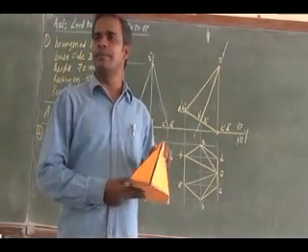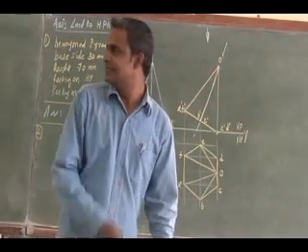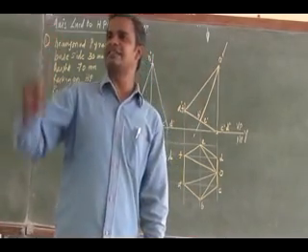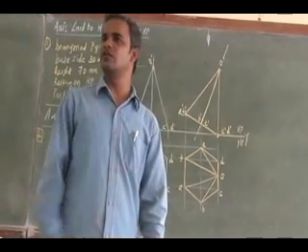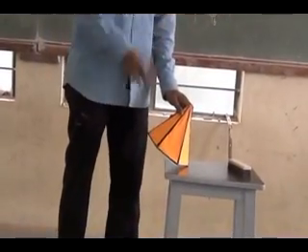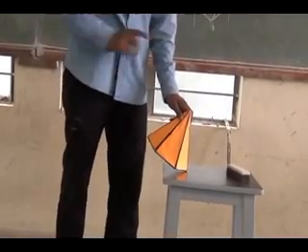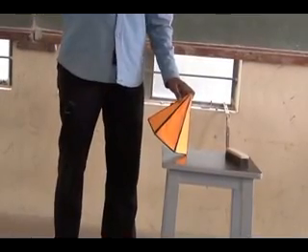The hexagonal pyramid is resting with one of its base corners such that the slant edge containing the resting corner is vertical. Instead of saying it is parallel to VP, it says vertical. Vertical means it should be vertical and it should be parallel. If it is vertical, then this is the orientation. Then the problem is the same.